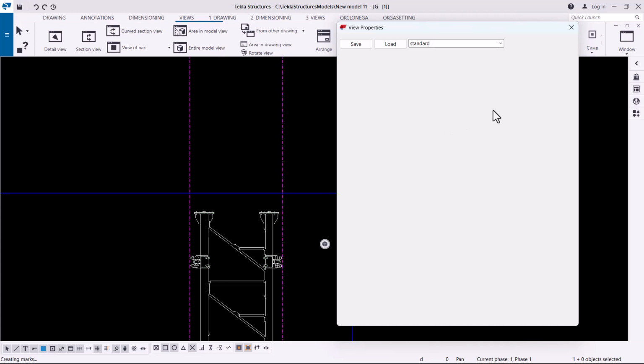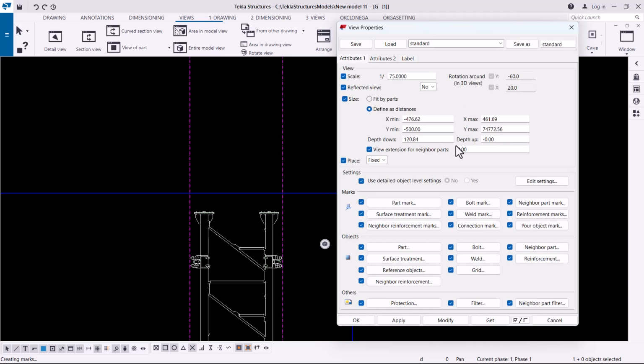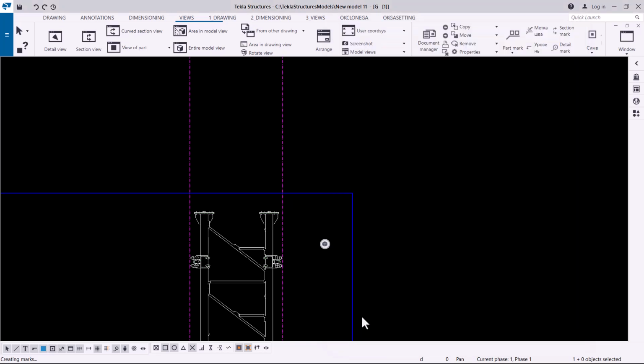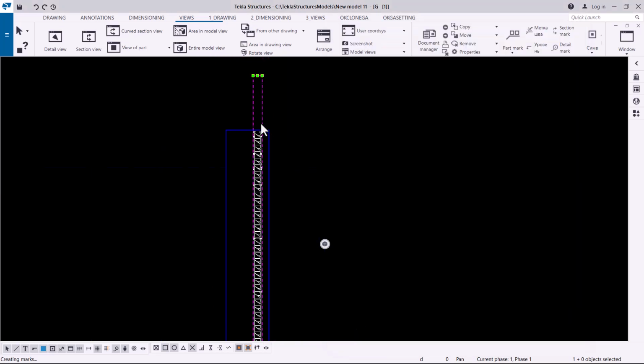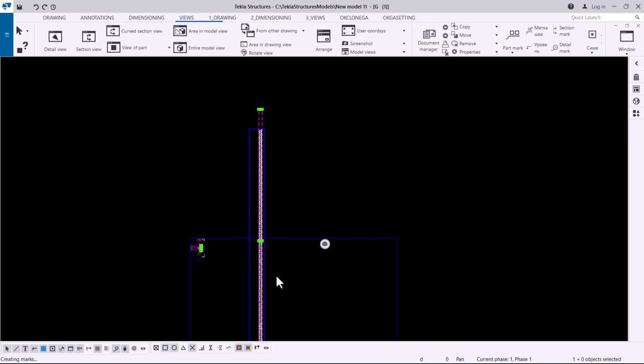Like you can see it's loading. You can see here it was some 120 or that. So this should be 74. Just key in the utmost height there, and it will open up everything, the full height. Just key in a height bigger than the height you have, and everything will be revealed. And if you click modify apply, everything will be okay. Instead of dragging it as I was doing, it will save you some time. So we have created this.